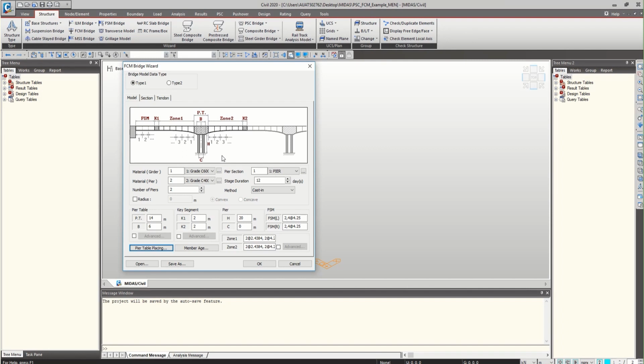Next, moving on to the inputs for Zone 1 and Zone 2, which are the lengths of the segments located to the left and right of the first interior pair table, we can then set, let's say, an arbitrary value of 12 segments at 4.75 meters each. So let's just copy that to the zone 2 input.